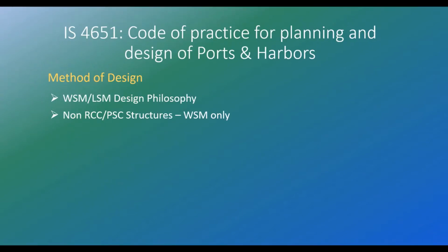Now we are moving on to the design philosophy. The code allows both working stress and limit state method of analysis, with more emphasis on working stress method. However, if you are designing a structure other than that of RCC or PSC material, only working stress method is to be followed. And it is not uncommon to use timber as a material for piles in harbor structures. Such a scenario mandates use of working stress method.